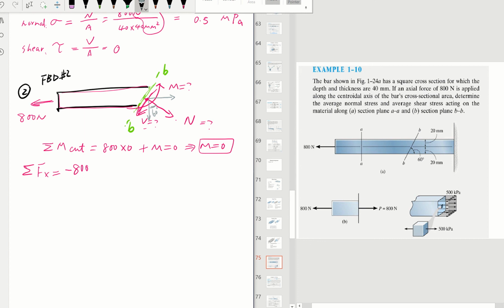You can go ahead and verify it, but we have done this in statics. I'm just going to move on. This is going to be 60 degrees. If that's 60 degrees, our x component right here would be what? That would be our N times sine 60 degrees, because this angle is 60 degrees as well, and that's opposite, using sine. So it's N times sine 60 degrees. And it's positive since it's going to the right. That's our normal.